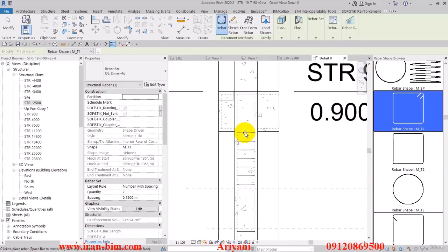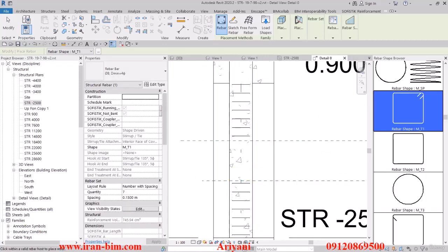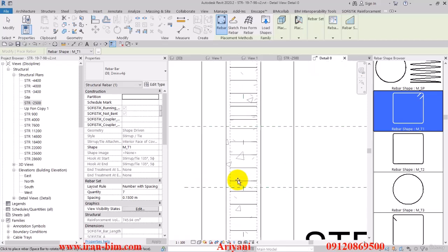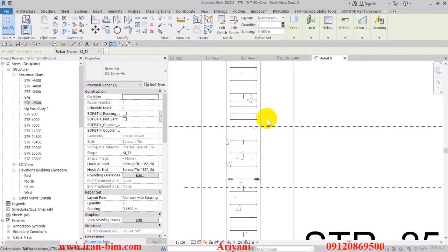After that, we have the middle part. The middle section goes from minus 2.5 up to the height of plus 90, and here it says the same thing in the plan, 7 type 10 rebars with a spacing of 15. But we can't really fit 7 rebars here. This is an AutoCAD file issue. Here you have to fix the issue yourselves. So then we'll select this. And then let's see what number we should choose.